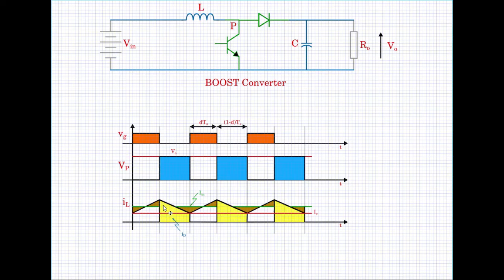So you will see the capacitor, this triangular portion up, charging the capacitor, and this bottom white portion here I am indicating is the capacitor discharging into the load. This area should be same as this area. This triangular upper area and this area should be same to have charge balance. We will look at that shortly. So this is how the current wave shapes come into picture.